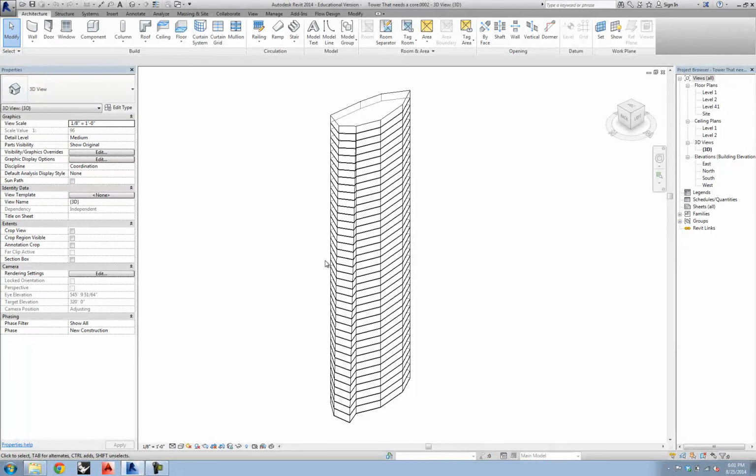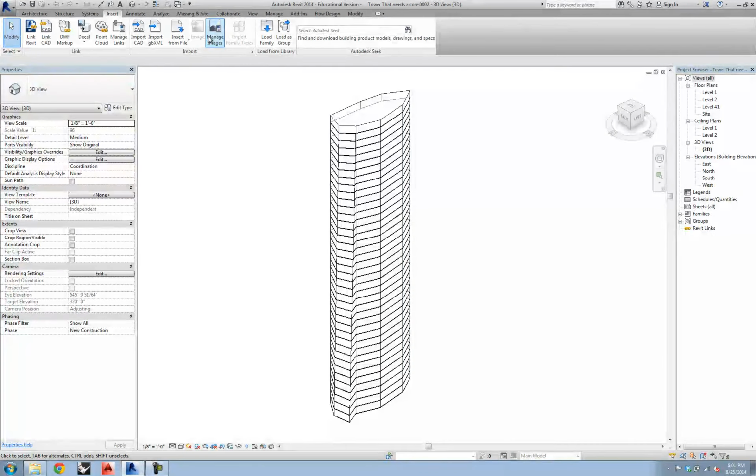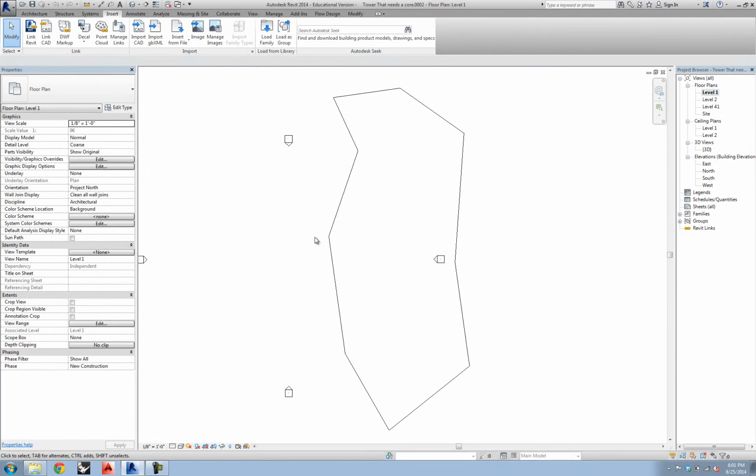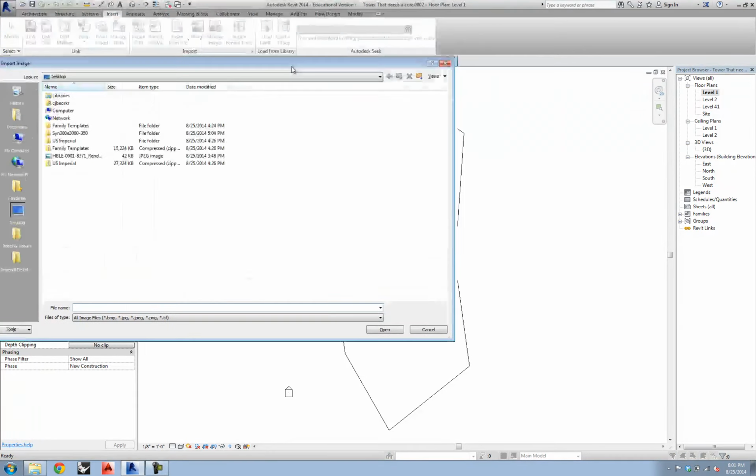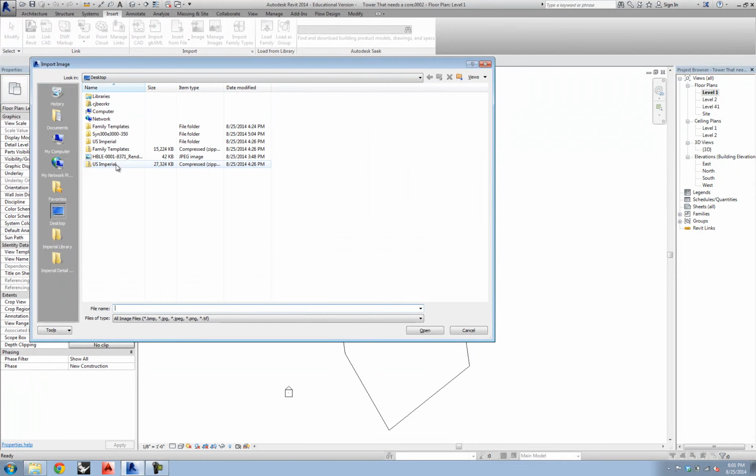Okay, here we are. We've got our tower model. I've already got the floor plates in it. I downloaded this from the Moodle's website. We want to first insert our image into this file to reference from the Westbrook Tower by Mies van der Rohe. In order to insert that image, we'll go here to the Insert tab and the Image folder.